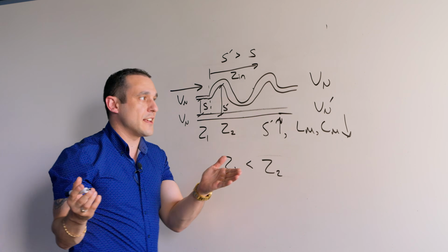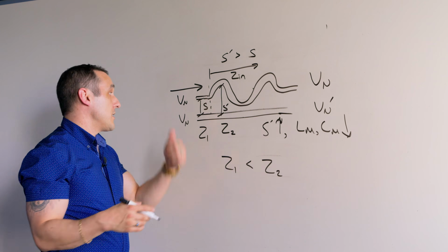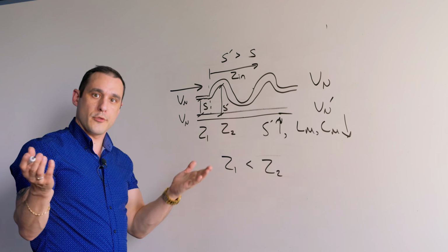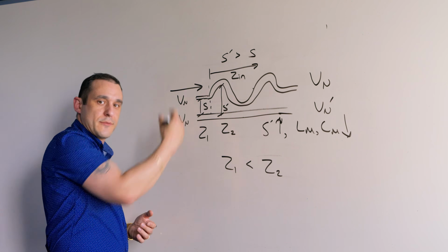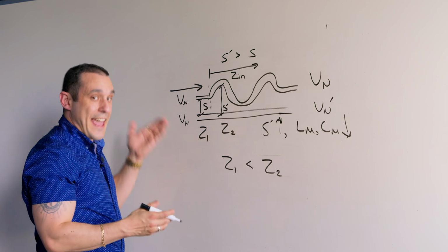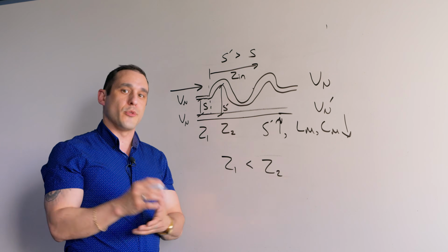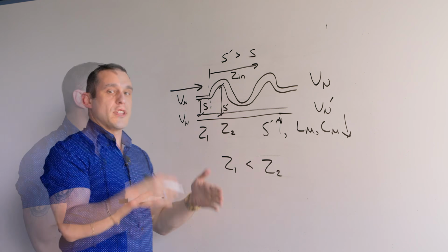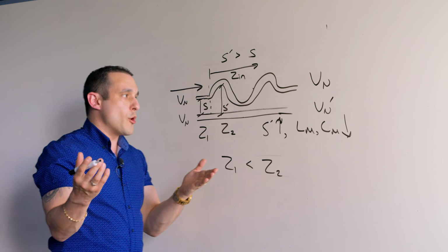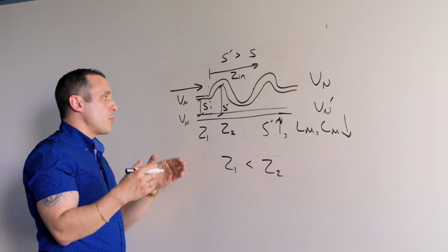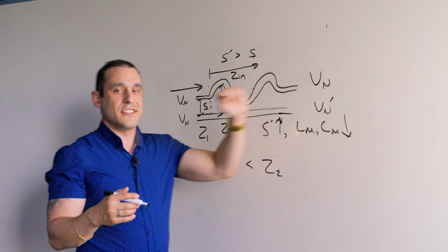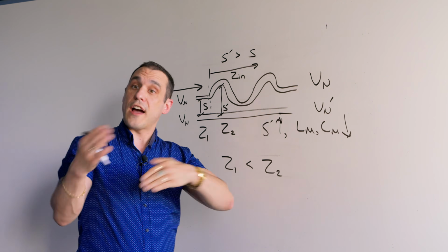And the reason for that is the differential receiver can kill this common mode noise, because differential measurements basically take the difference between these two signals and that cancels out the noise. That's the whole point of using differential pairs. It's one of the major points of using differential pairs. So that essentially explains what mode conversion is. It is a conversion between common mode and differential mode signal, or vice versa.